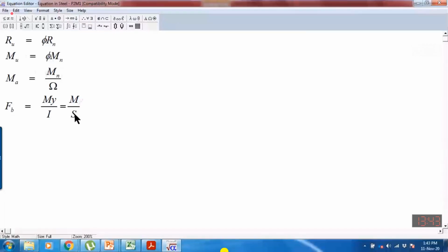So this will be the section modulus about the x-axis or y-axis. So M is the applied moment, or Mn is the moment carrying capacity. The moment carrying capacity can be computed if a beam is already designed. Then we can bring Mn on the one side.